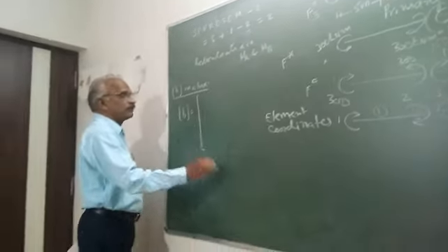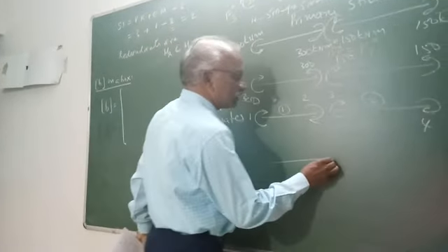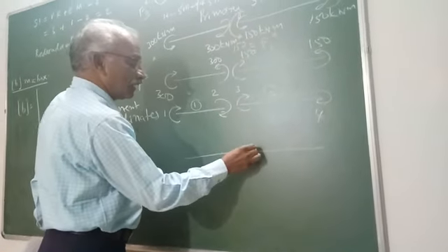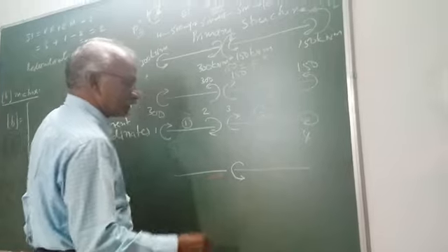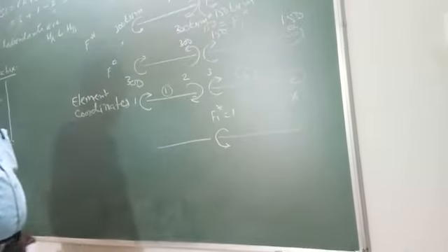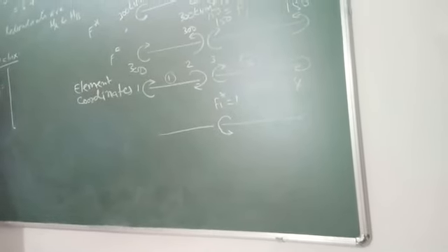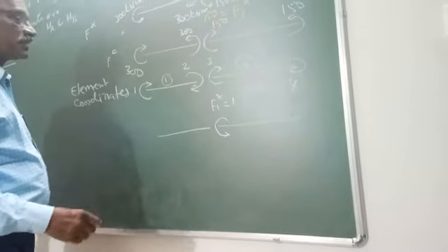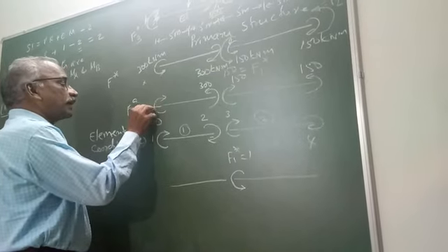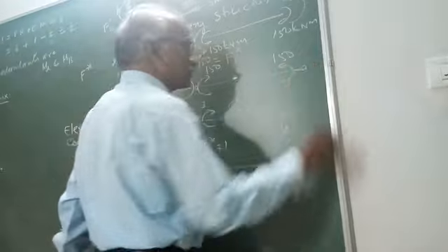we have to apply unit force along F1 star. These are the elements. This is F1 star equal to unity. We have to apply unit force one at a time. Now we have treated this as hinged. Actually, this is hinged here, and here also it is hinged.